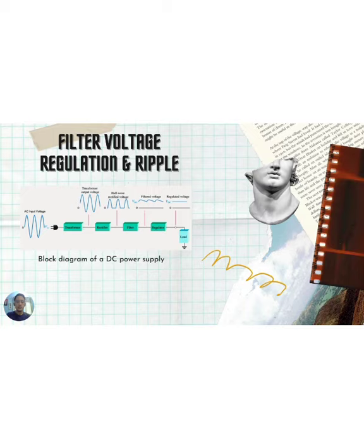So next, ideally, a power supply filter eliminates the fluctuations in the output voltage of a half-wave and full-wave rectifier and generates a constant level DC voltage. The elimination process is important because many electronic circuits need a constant or consistent source of DC voltage and current to supply energy and power biasing for proper performance.